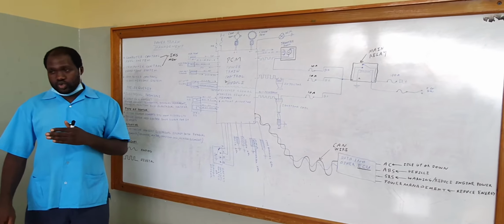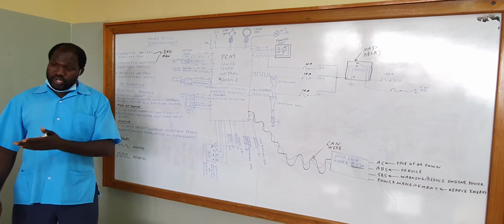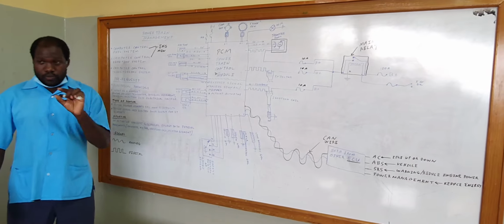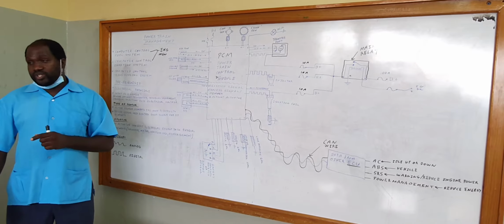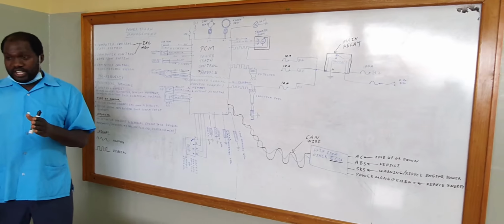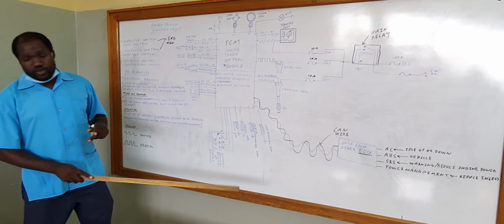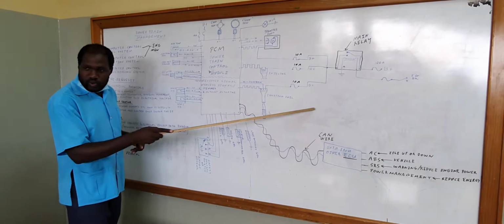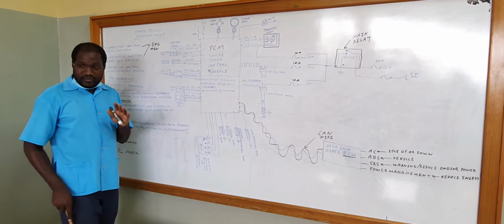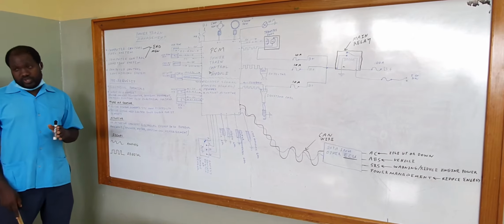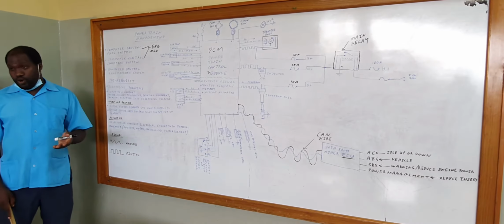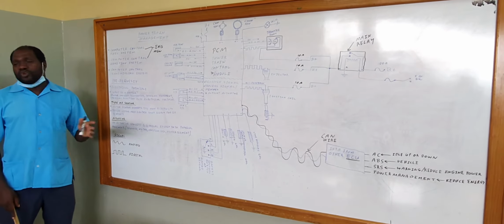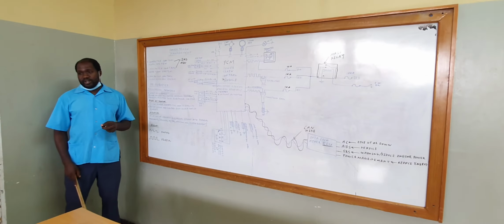And some vehicles will show it. For example, even the 2005 Honda Civic. When you scan it, you don't see the code, you just see a number, like 22, 4, and those things. And some scan tools can give you the option to show a P code, whatever it is equivalent to. Because the vehicle is not originally OBD2. So you can still sell it in Europe, Eastern Europe, Western Europe, but you can't sell in America, because in America you have to have an OBD2 protocol to operate in their market.